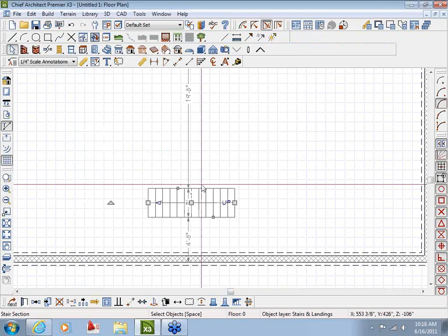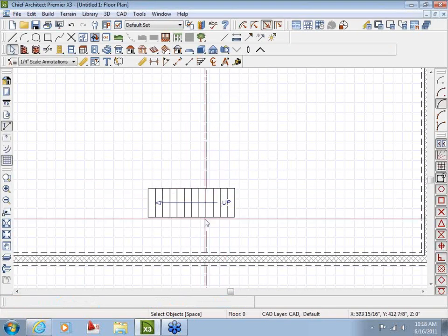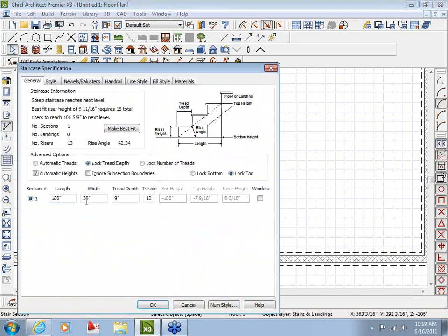Now this will work for any house. This will work for basement stairs, for ranch stairs, for cape stairs, and for a two-story with the L shape. As long as you're under that 8 1/4, you're going to match the stair that we're using here at Ritz-Craft. So now we have the geometry right. I know I want 36-inch wide. I have my 9-inch tread, and I have them locked. I have my treads, and it's under 8 3/16. So I'm good to go.